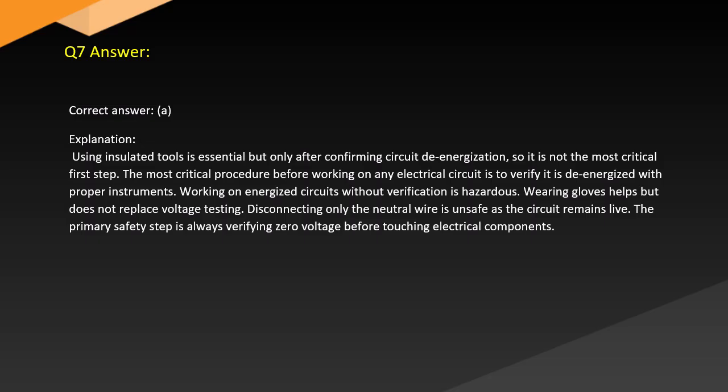Wearing gloves helps but does not replace voltage testing. Disconnecting only the neutral wire is not safe, as the circuit remains live. The primary safety step is always verifying zero voltage before touching electrical components.